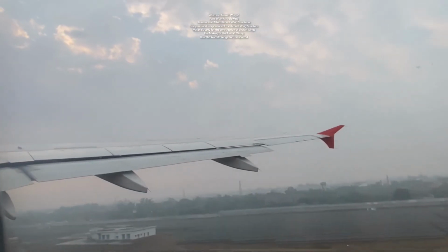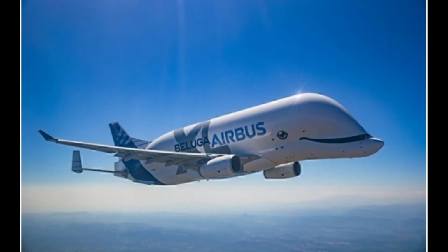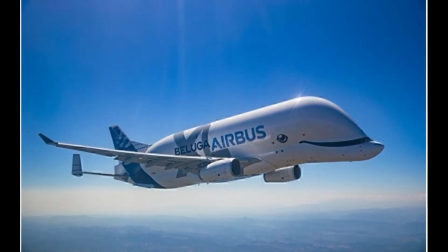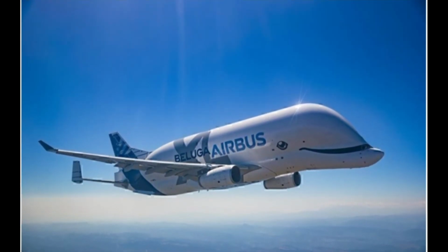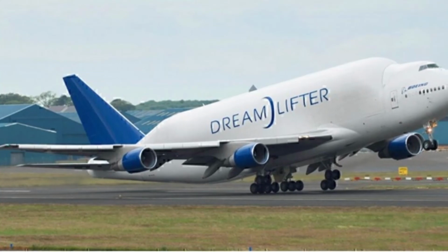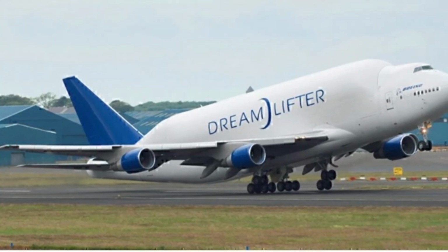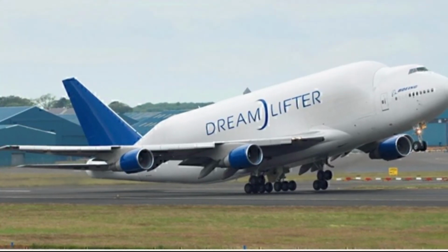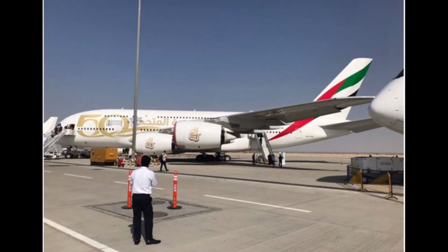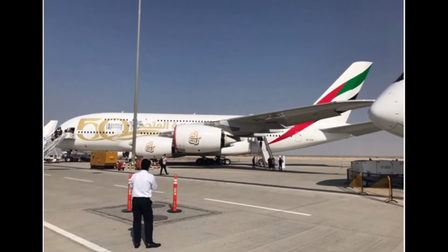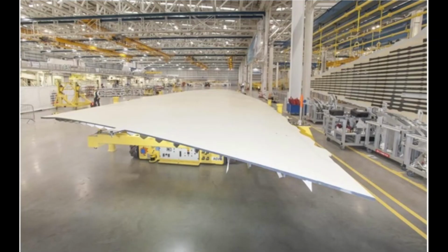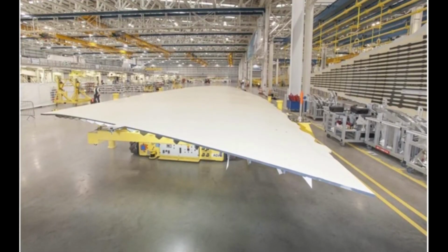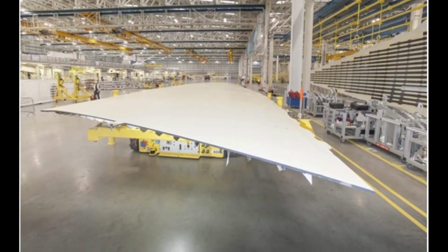Drill hole. Chamfer hole. Ream hole. Lubricate hole. Tighten rivet/bolt. Install rivet/bolt. After drilling is performed, care must be taken to ensure there are no burrs on the other side. Such burrs could puncture the paint when the skins are fastened together. Thousands of fasteners are used in the wing structure. Composite structures are bonded into large sub-assemblies, rather than riveted. However, the final assembly of the wing structure would still require installing rivets and bolts.